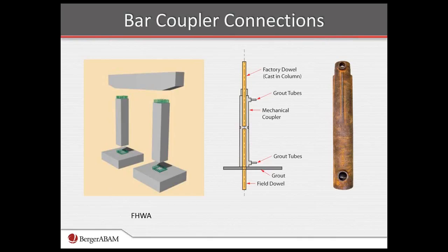So the attendant stiffness of the combined bar, mechanical coupler, grout element in a plastic hinge zone can alter the deformation capacity and the distribution of curvature over the column in a plastic hinge zone. And so until fully proven, that's why we're saying these couplers and this hardware should go into the capacity protected adjacent element if at all possible, and certainly in the higher seismic categories.